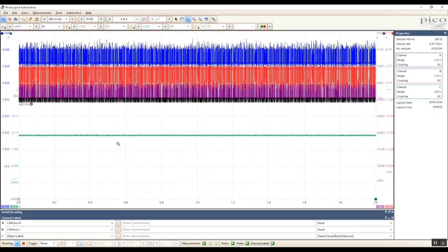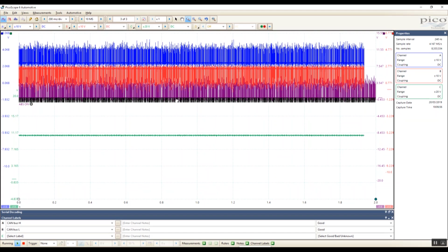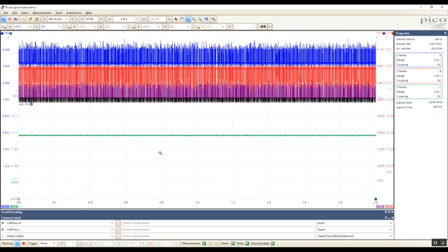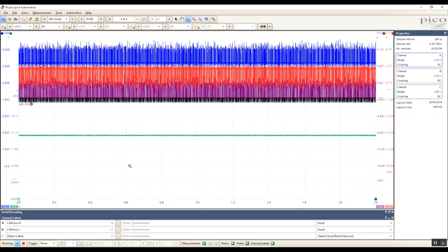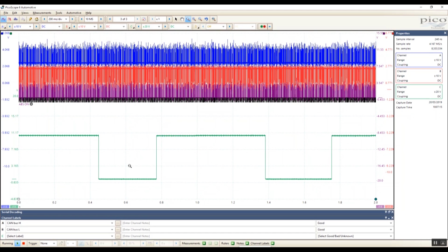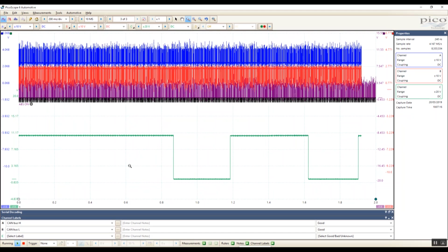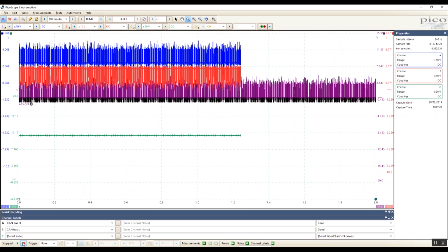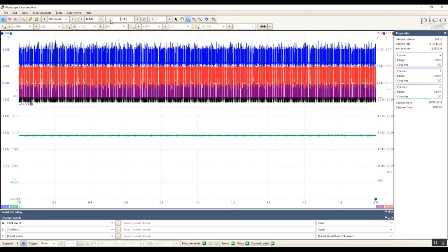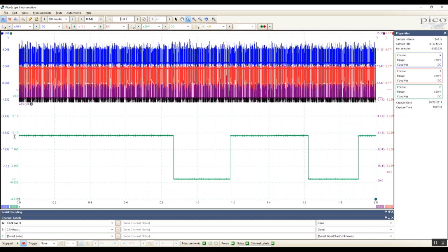So the plan is to operate the brake pedal a number of times and see if any of the data bytes change from ID 1A0. So let's go and do that. So let's stop that capture and just go back through the buffer. So here the brake pedal is at rest. This is brake pedal on, off, back on again here.